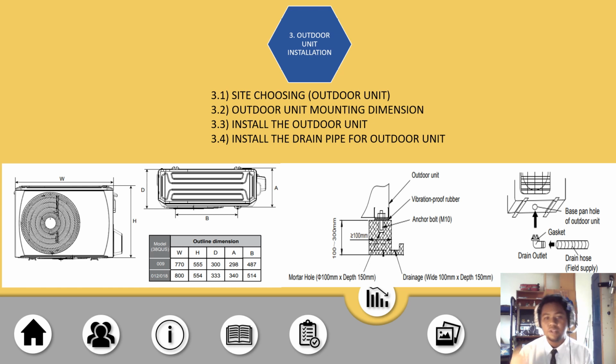First of all, the outdoor unit should be well ventilated and free from obstacles near the air inlet and air outlet. The space should not increase the operating noise or vibration of the indoor unit and the outdoor unit, and the space should not cause any drainage problem with discharge water.